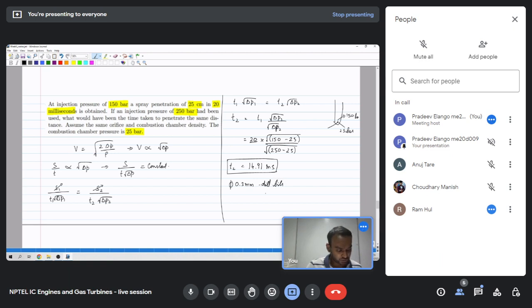And with hydro erosion we can achieve diameters up to 0.15 or even 0.125 mm. The recent common rail injectors are formed by hydro erosion. Maybe laser is also used in some cases. These are the things that I know of.